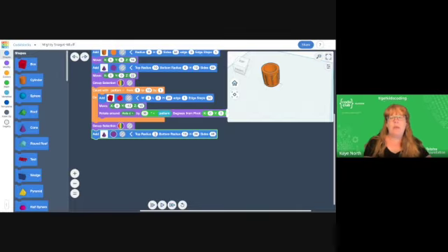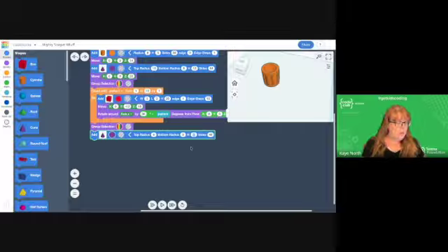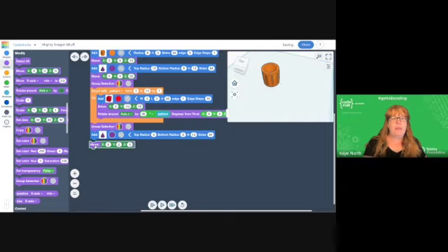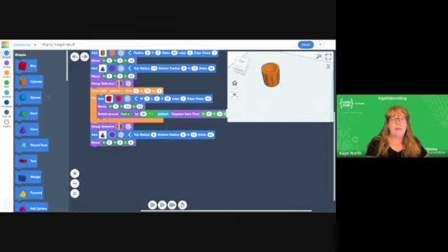If you remember, the cone that we cut out had a radius of 6 and 10. We need this to be just a little bit smaller, so our top radius is going to be 5. The bottom radius is 9. We will continue with the height of 12, and we will also have 64 sides, exactly the same. Let's put that into a position, so it's going to move to 0, 0, and 6. We're going to add in that cylinder to join the 2 cones together, remembering it is a solid shape.